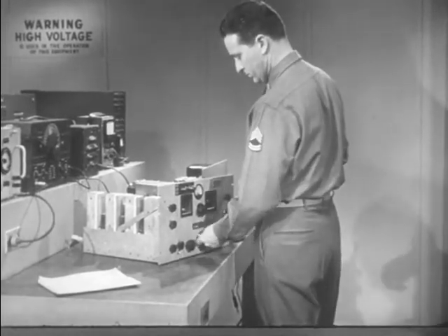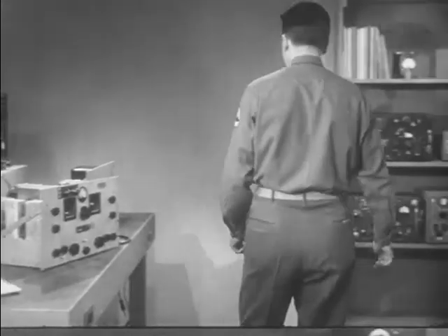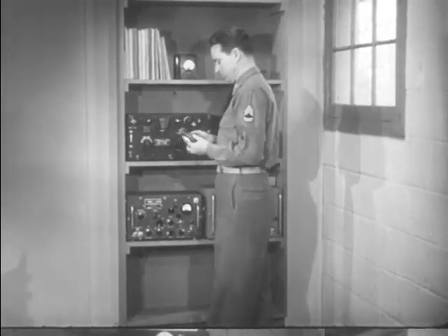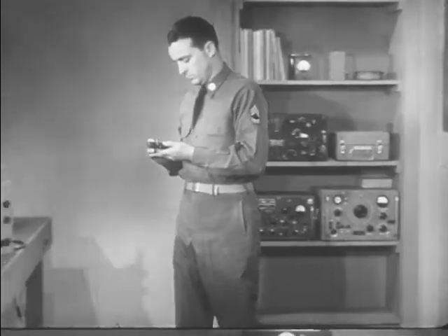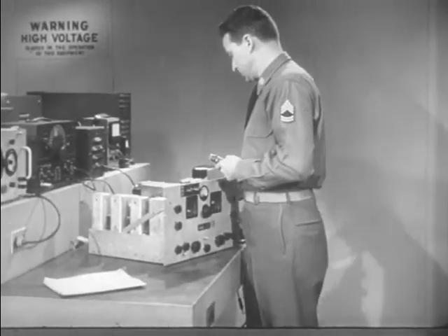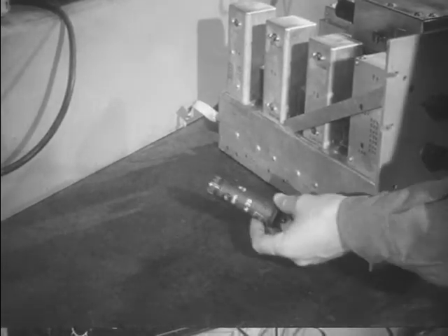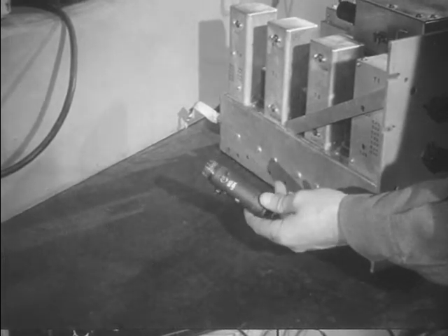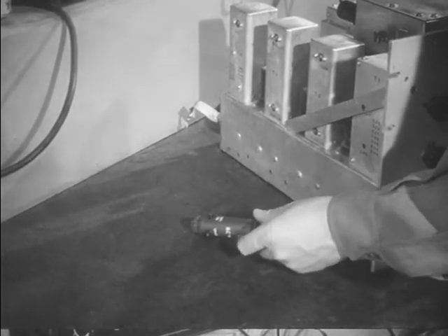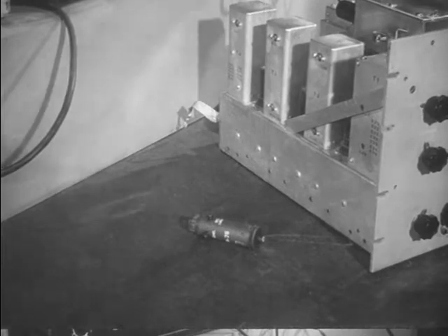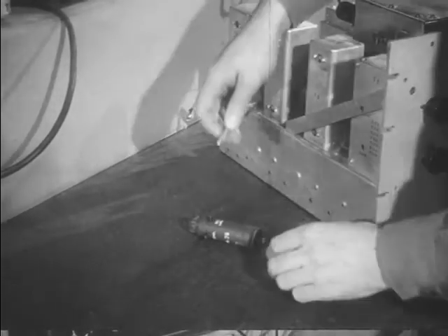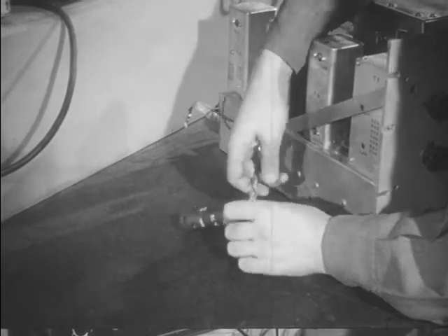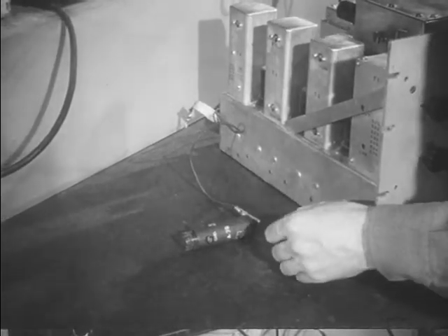Now, with some understanding of how a signal is generated, let us put it to use and test a radio receiver. A signal generator is not connected directly to the equipment to be tested. If a radio receiver is to be tested for sensitivity, a phantom or dummy antenna is connected between the signal generator and the receiver. The phantom antenna simulates a real antenna in that it roughly duplicates the electrical properties of the real antenna.